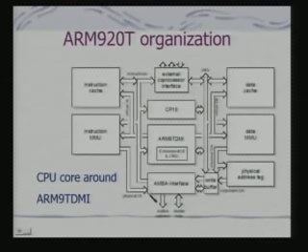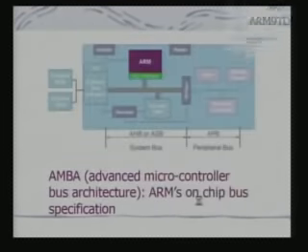And this is your external coprocessor interface, and this is the AMBA interface. AMBA is an interface protocol for the definition of a bus. In fact, AMBA is Advanced Microcontroller Bus Architecture, which is ARM's on-chip bus specification. Just like on your PC, where you have a PCI bus definition, AMBA is an on-chip bus definition. This is basically your bus structure, and this is your bus interface with the ARM, and these are the other on-chip peripherals which can be connected.